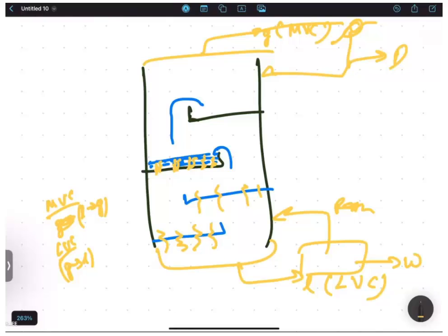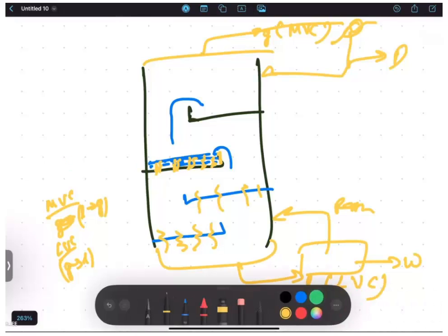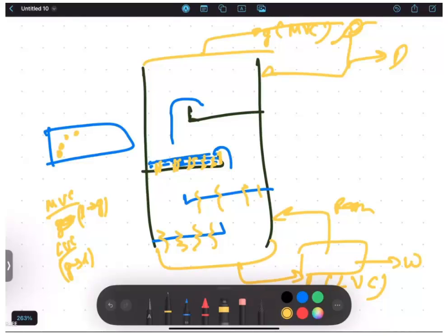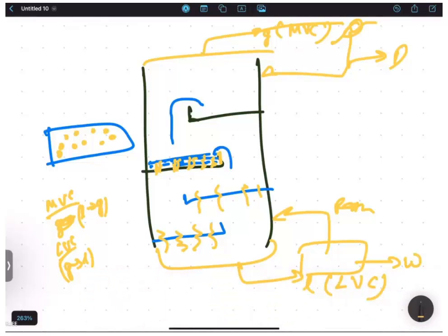So we're trying to make you understand now. Suppose this is a tray. Here a liquid pool is formed. This blue pool is known as the liquid pool. From here, the gas will bubble through the liquid, contact will happen, and mass transfer will occur. So what we assume is that, suppose this is a liquid pool, gas will bubble through it in the form of bubbles. What we say is that the contact time for each bubble is the time of contact between the liquid and the bubble: for how much time this bubble will form here, then rise like this, and burst here.